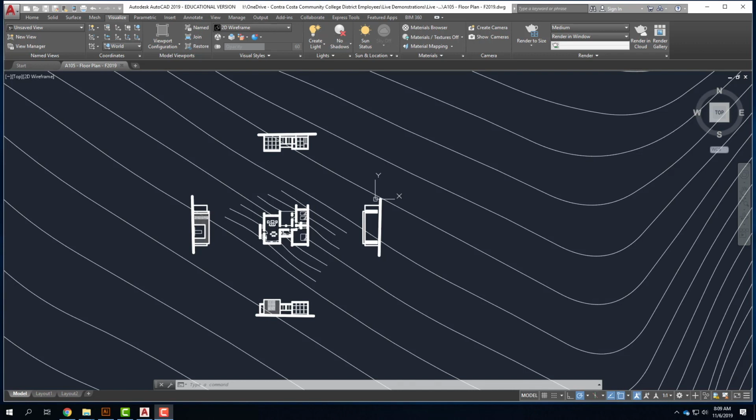So as we get started, everything that I've drawn so far is in Modelspace. We can tell that it's Modelspace because of that black background with the white lines. When we switch over to Paperspace, AutoCAD's really good at differentiating. It's going to be white background with black lines. So as soon as you flip over, you think piece of paper. And essentially the reason that it's called Paperspace has to do with a piece of paper rather than the full-size drawing that we've been used to.